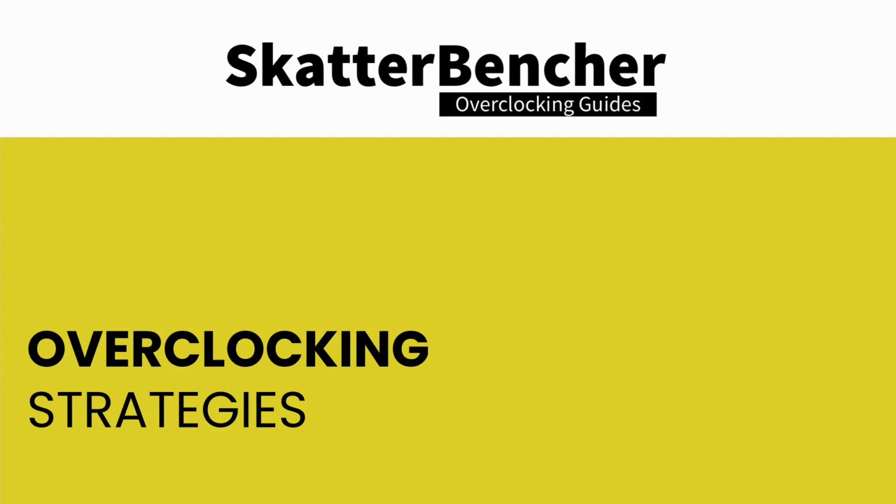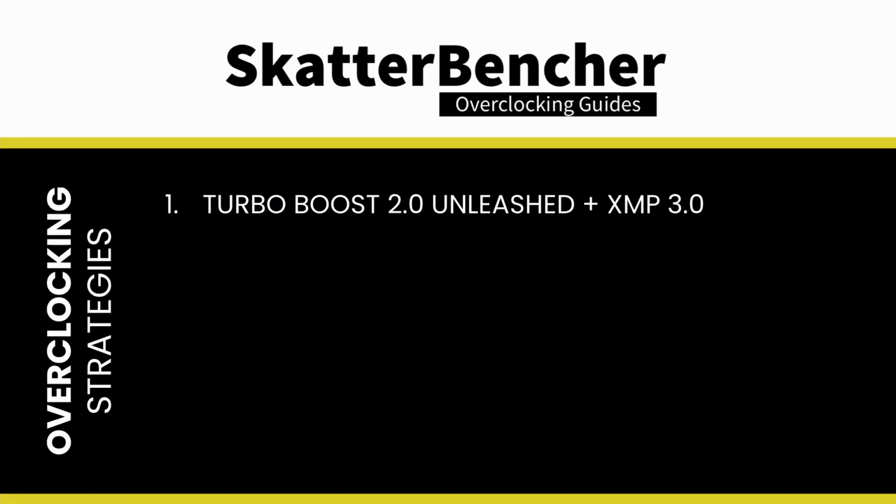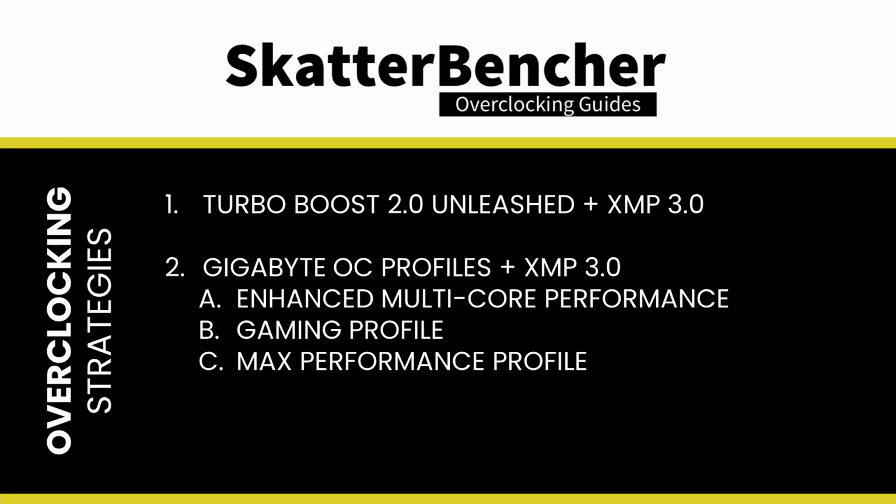In this video, we will be covering three overclocking strategies, starting out from the easiest one going to the most complicated one. First, we increase the performance headroom by unlocking the Turbo Boost 2.0 limits and enabling XMP 3.0. Second, we test out three OC profiles available in the Z690 AORUS Master BIOS. Lastly, we do manual overclocking to get the most performance out of our system. However, before we jump into the benchmarks, let's first have a look at the hardware and the benchmarks that we'll be using in this guide.